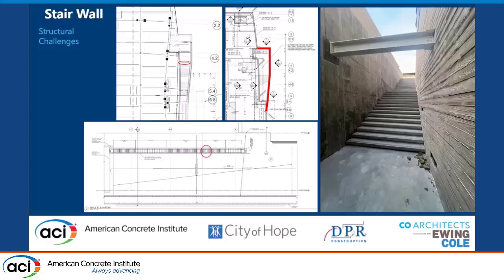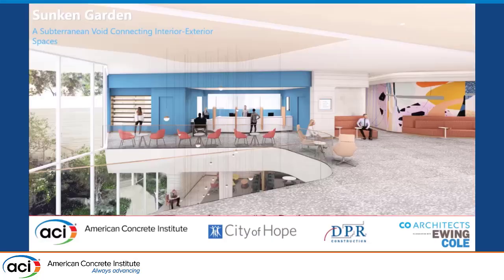In traditional retaining wall design you do one-way design, but in this case we had to do a finite element analysis to find the distribution, and we had to introduce an element that starts with the S. I think that word is forbidden here, but it's to cut down the span. We'll go into more detail on the next wall.